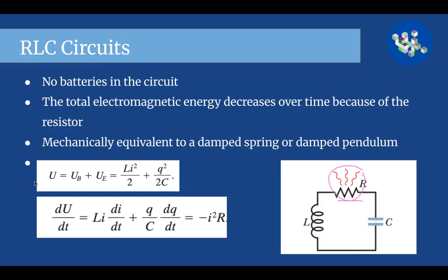And it's mechanically equivalent to a damped spring or damped pendulum. I'll show you later why that is so. All right, and then if we're looking at the energy stored, that'll be the energy in the inductor, which is Li squared over 2, and then the energy in the capacitor, which is Q squared over 2C, right?